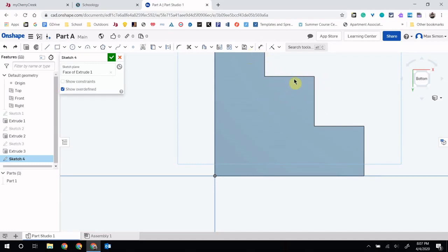So if we didn't do it that way, we could also just do it doing math. If you can't get these to work for you, that's okay. Let's say you're just going to get a circle going, and you can dimension that out. You're going to dimension that out by just clicking on the center of that circle and clicking on that line and telling this that you need it to be half of 15.